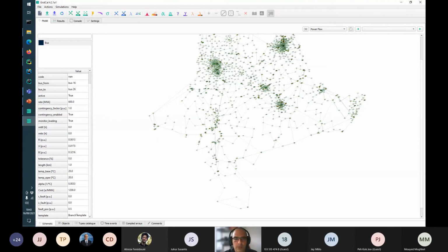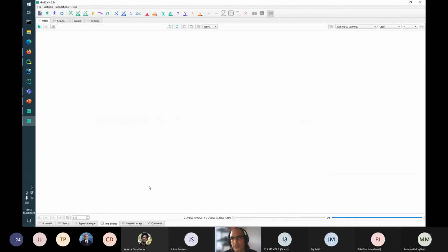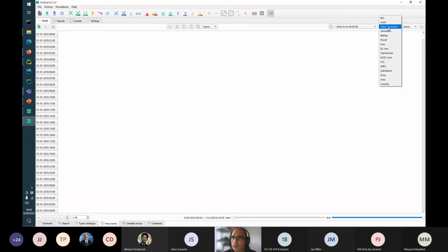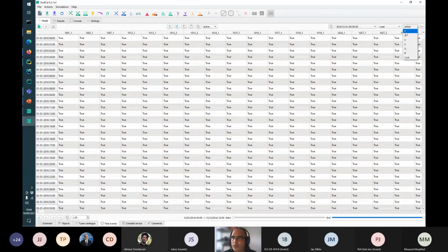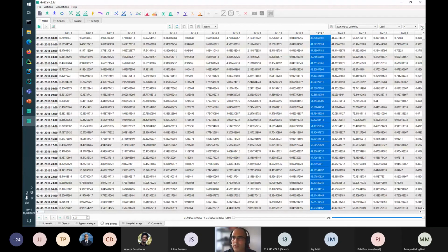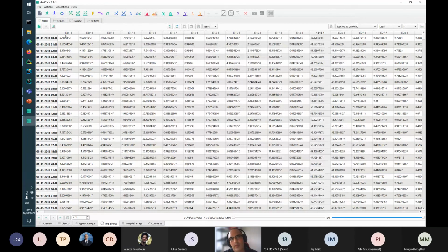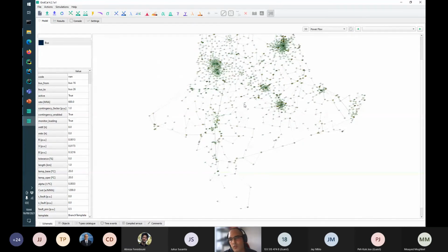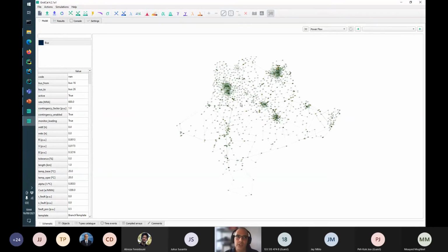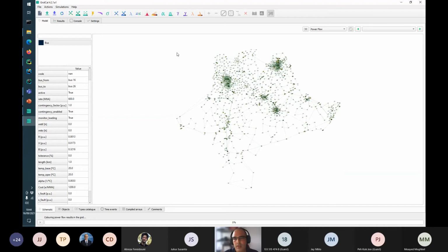I also extended this Texas grid with some random profiles I have around. And there you go. It is different for every node, but it looks like this. It's a complete year, you can imagine. But since this grid is quite large, maybe I don't want to run the complete power flow because I'm in a hurry. So let's just use the linear analysis based on the PTDF. And this one takes really no time compared to the traditional power flow.